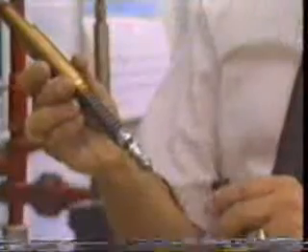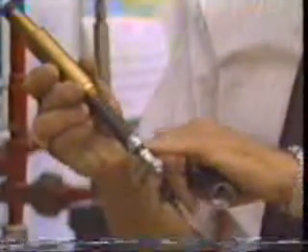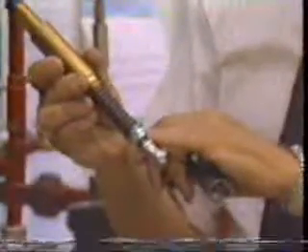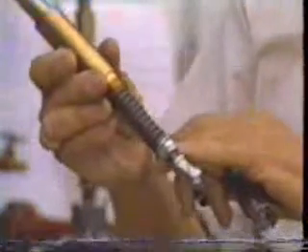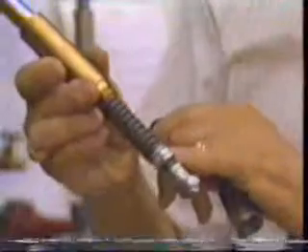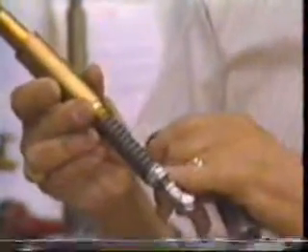Now, with a spring-adjusted valve, as you see here, the desired calibration pressure is obtained by adjustment of this nut against this spring. By tightening the nut tighter against the spring, we have a higher calibration pressure. By loosening the nut away from the spring, we have a lower calibration pressure. Now, an experienced valve mechanic can set this nut pretty close to the desired calibration pressure the first time, but he's only going to get it pretty close.